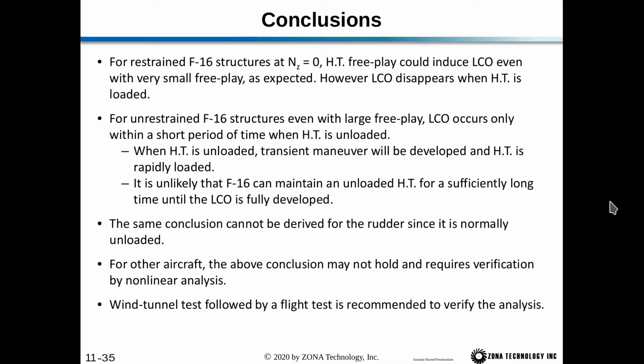So the conclusions here from this case study is for a restrained F-16 structure at NZ equals 0, the horizontal tail Freeplay could induce LCO even with a very small Freeplay as expected. However, the LCO disappears when the horizontal tail is loaded. Now for an unrestrained F-16 structure, even with a large Freeplay angle, LCO occurs only within a short period of time when the horizontal tail is unloaded.